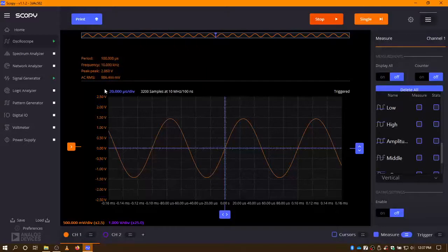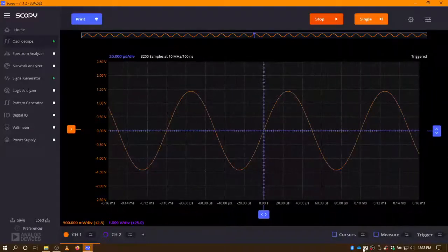And now you see here, I have my information, and I chose the peak-to-peak value of 2.828 because that will represent pretty much 1 volt RMS. And I'm pretty close to that. Right now it's saying I'm at 986 millivolts RMS. So that's one of the features for all oscilloscopes, whether they're bench mount or the digitizing USB style. You can do measurements so you can get the precise information. I'm going to shut that feature back off.